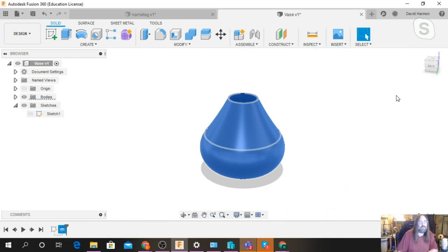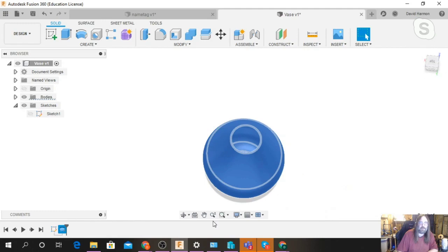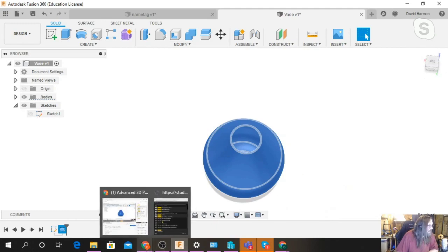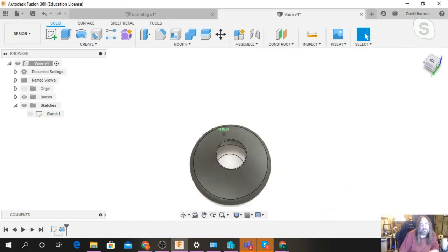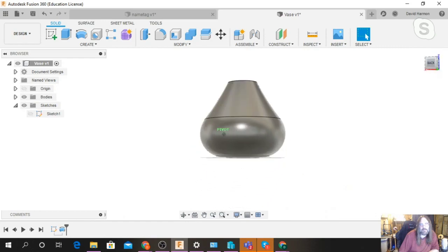We have our vase. Now, we're going to talk about it on Tuesday, but 3D printing slicers have an amazing feature called spiral vase mode or spiralized contour. So you can actually print a solid, in defense of the other method, as a vase. So that's exactly the steps to make a semi-solid vase.